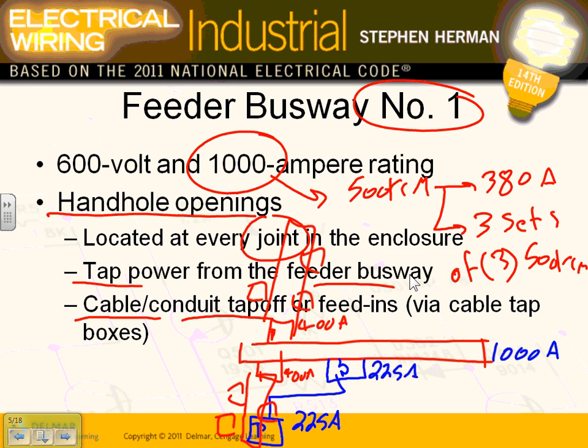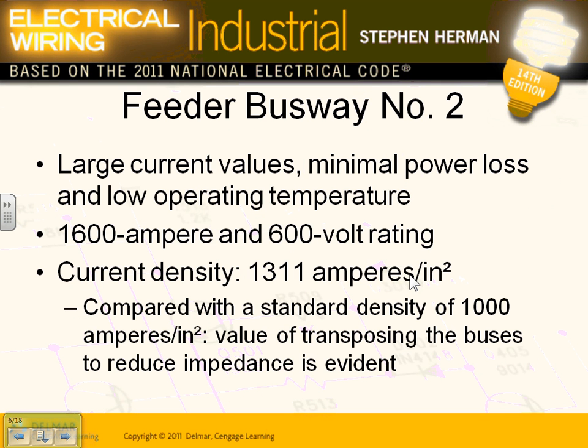If you look right here, here's where the substation is. The substation has 2 disconnect means, 1600 amp and 1000 amp, and these 2 disconnect means, fuses or circuit breakers, are actually feeding the whole load in the whole building. The substation has only 2 circuit breakers. That's a major advantage of using busways. Busway 2, guys, and the one in this book is 1600 amp.